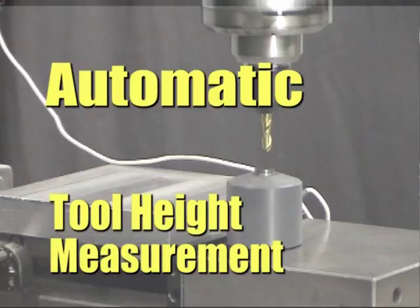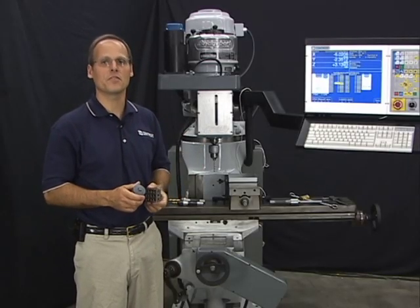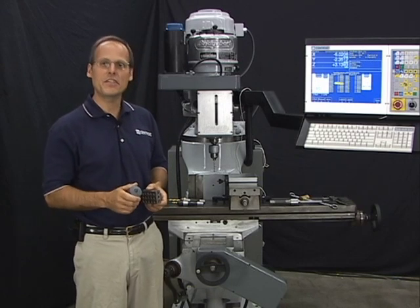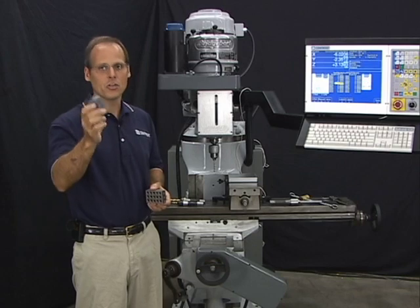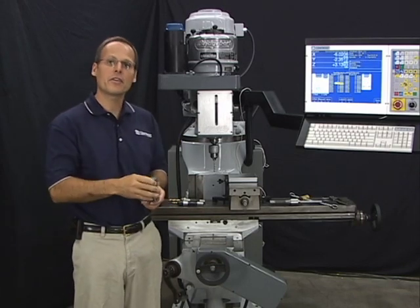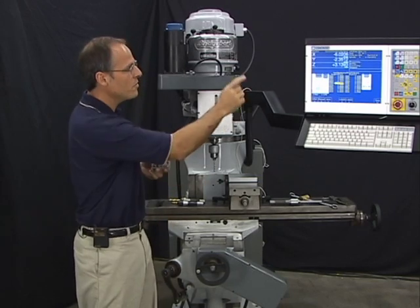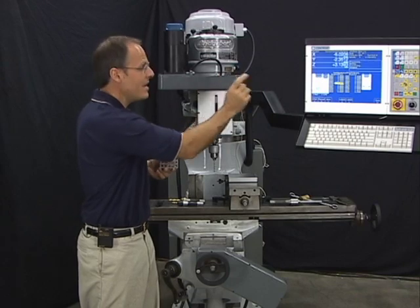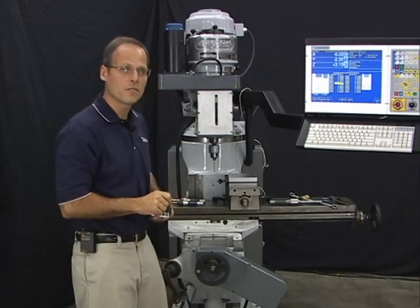Now that you know how to set tool height offset values manually using a 1, 2, 3 block and a reference tool, let me show you a faster, easier, and much more accurate way with the Centroid optional TT1 TouchOff Block. The TT1 plugs into the back of the control, and the control will automatically jog the tool down, touch off the block, and record the tool height offset value in the library for you automatically. Let's go check out how it works.